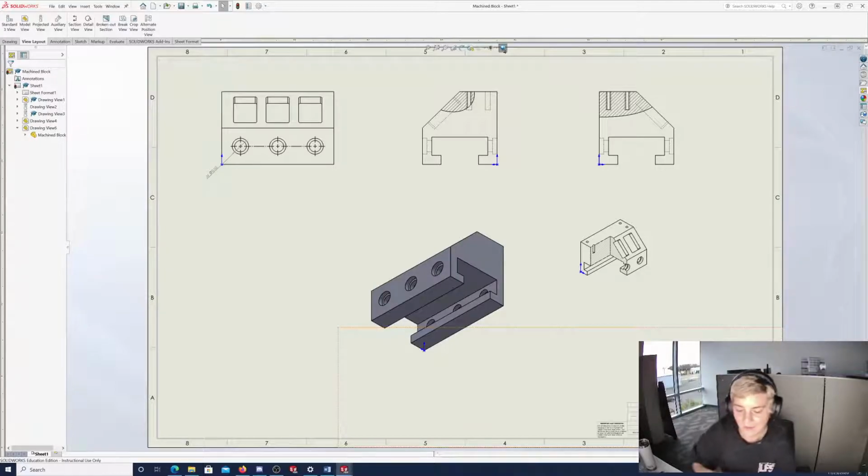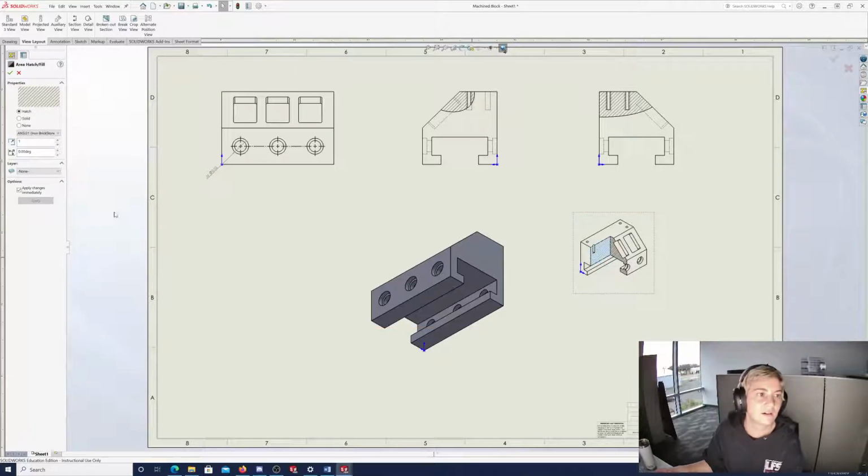Cool. Alright. So we added a cutaway view. We added a different configuration. We added cross hatching. So we're on page 1620. So you can modify your crosshatch properties. I just showed you guys that too. So let's select this crosshatching here.